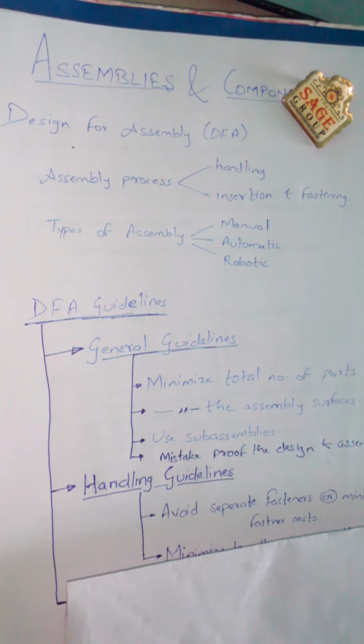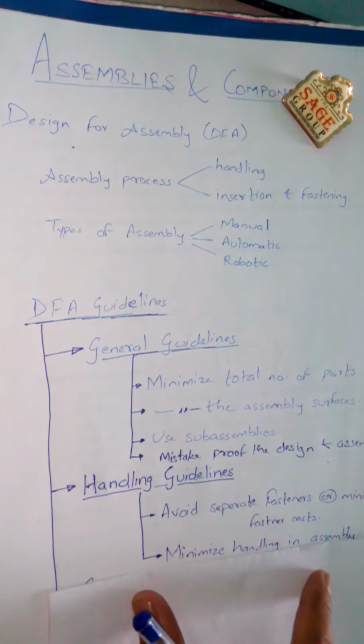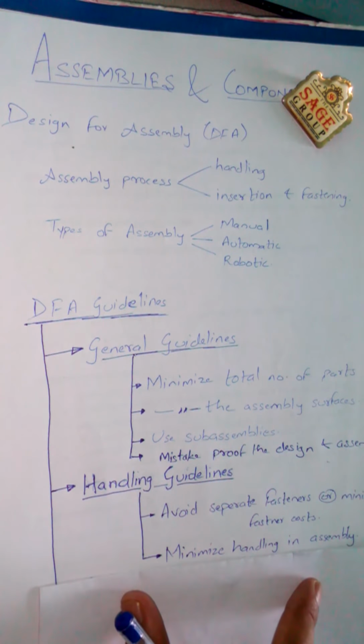Alright, so when the design permits, use fewer large fasteners rather than several small ones. Costs associated with fasteners can be minimized by standardizing the few types and sizes of fasteners, fastener tools and fastener torque settings. When the product is assembled with a single type of screw fastener, it is possible to use auto feed power screwdrivers.